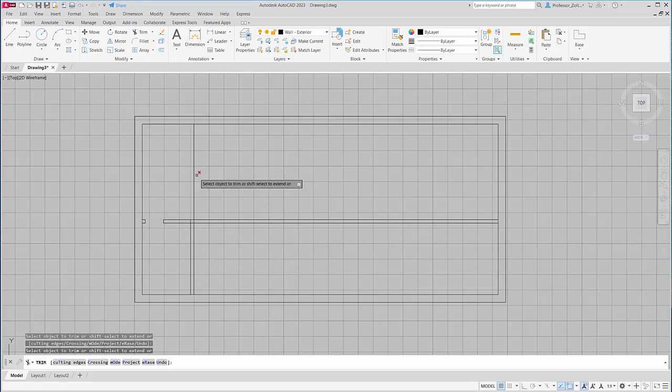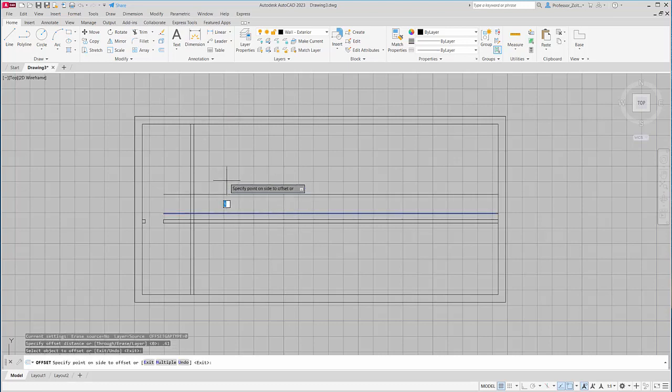So I can keep doing this and adjust the rest of the space. You'll notice that there I have another doorway above it at 0.2. 0.2, enter, click on the line, click on the side, and that doorway is 0.61 as well. Offset 0.61, click on the line, click on the side, and then there's a little bit of a space for the casing, and that's 0.1 meters.